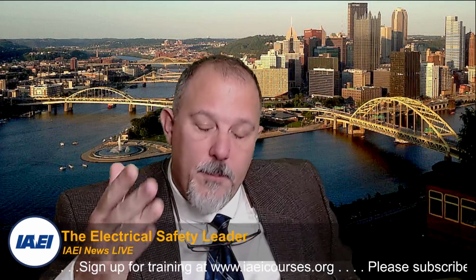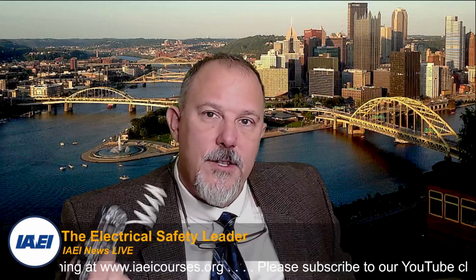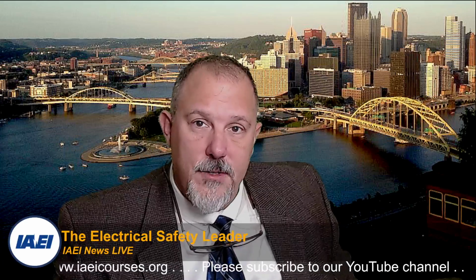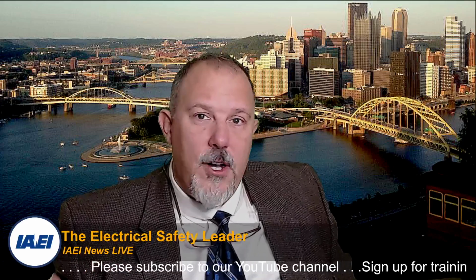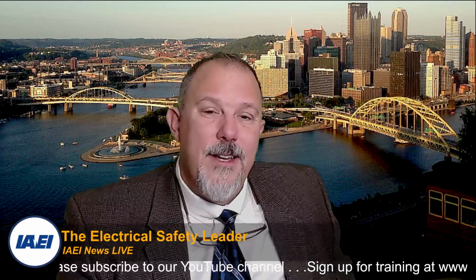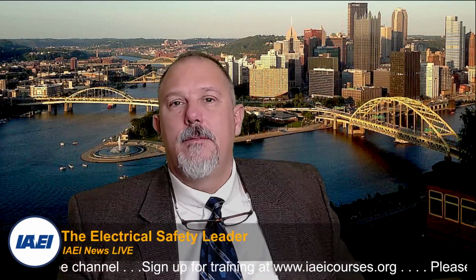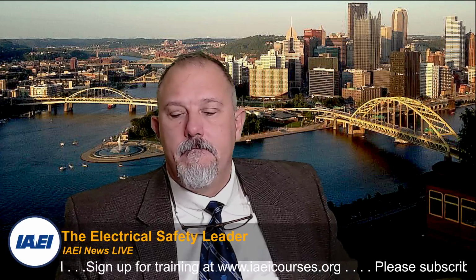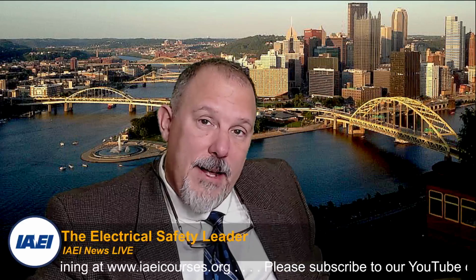Again, remember, if you're powering a pool pump and you have a 2-pole breaker, you don't need the neutral. You can use 2 hots. If you don't have an equipment grounding conductor, you just have a hot and a neutral in an older home, these devices will still work. I don't need an equipment grounding conductor. And I think that's just about it.